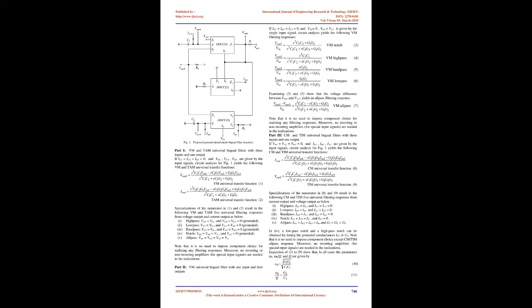The circuit in [34] uses 2 plus type FDCCIIs, 5 grounded/floating resistors, and 2 grounded capacitors. The circuit [34] has no need of any matching conditions, which includes no need of component and input matching conditions. Similarly, in 2018, the reported mixed-mode biquad filter [38] also uses 2 FDCCIIs, 4 floating/grounded resistors and 2 grounded capacitors. Although the filters in [33, 34, 38] use only 2 active elements and can achieve many important advantages, it was shown that the use of the complex active elements and many resistors was unavoidable.